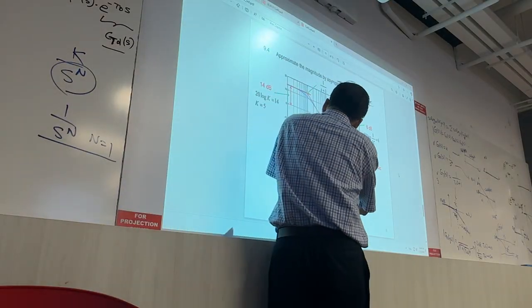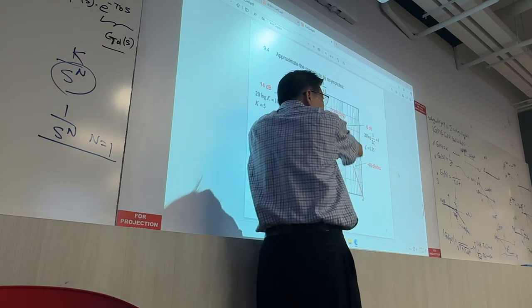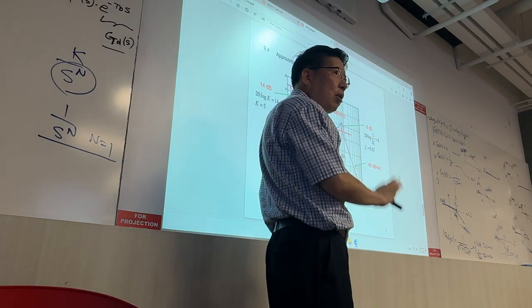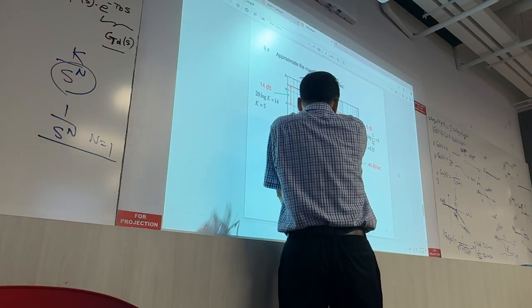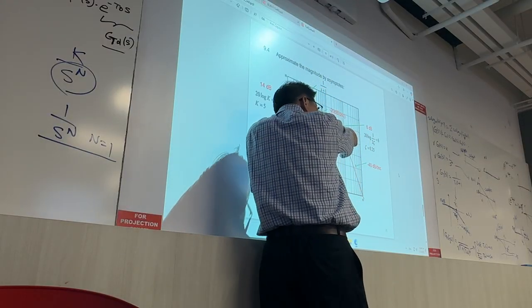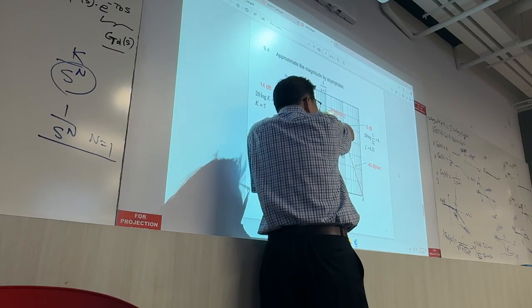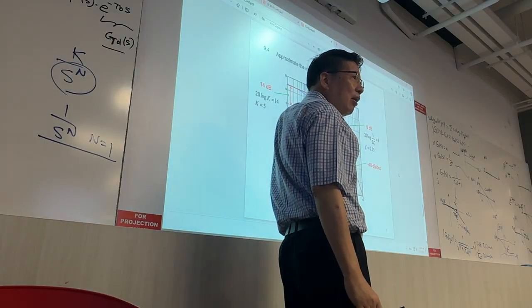So the corner frequency, you read it as a 9 or 10 or 8, it doesn't matter to me. So that is less critical. What I care about is that this needs to be minus 20 dB per decade. If you don't use that, you think you fit perfectly, that is not right.